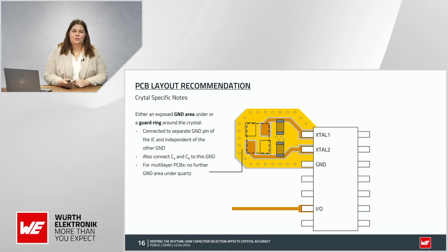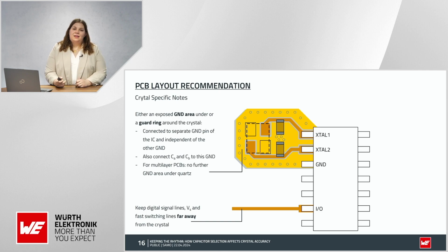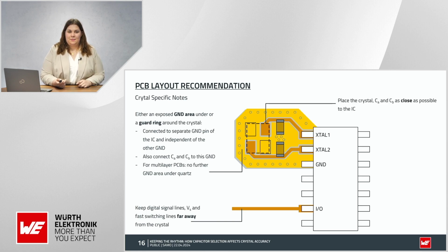So please make sure to have a separate ground. Also, you should connect your two capacitors to ground. And if you have a multi-layer PCB, please don't put another ground area underneath your crystal. Then, as I said before, keep any digital signal lines, power lines, and fast switching lines far away from the crystal, because they can interfere with your frequency.